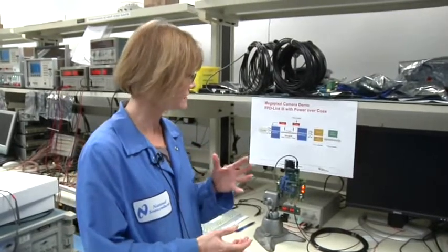And then for this in particular, for camera applications, we also focus on getting a very small package. So we're working to keep the die size down, keep the pin count down, and keep the package size as small as possible. If you envision, these camera modules are going to be stuck in various locations around the car, places where there's not a lot of room. So we put a lot of emphasis on minimizing on the serializer side in particular.